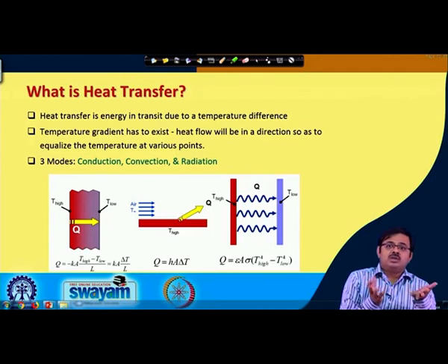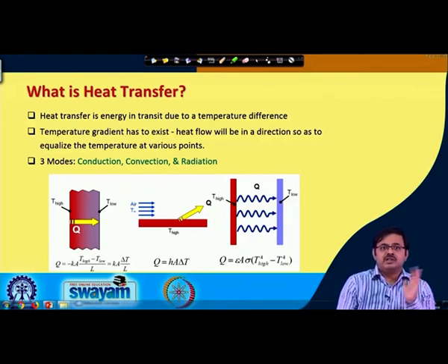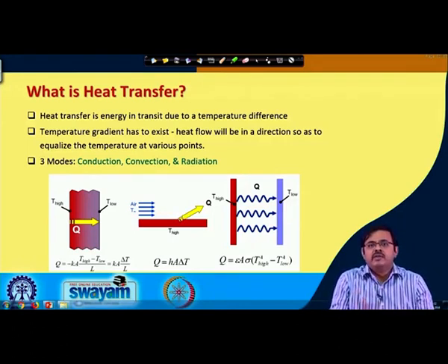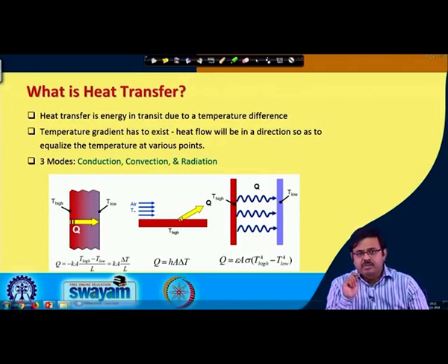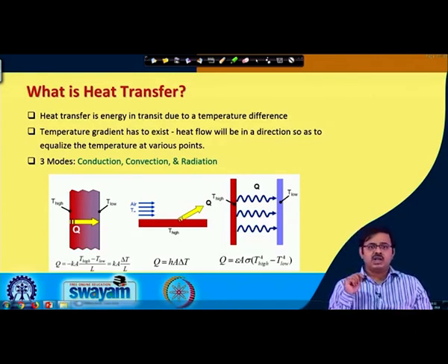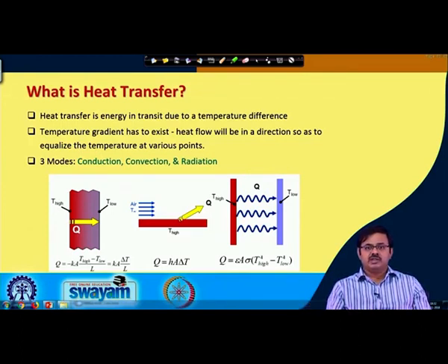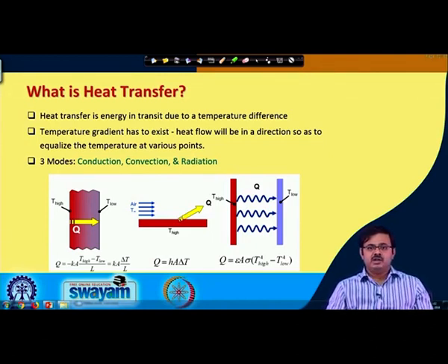And it also depends on boundary conditions in terms of what is the temperature, whether it is uniform temperature or non-uniform temperature, and so on and so forth. We will look at all those later. But what I am trying to say is, unlike a solid like copper, where the thermal conductivity is whatever, 400 watts per meter Kelvin at a certain temperature, for heat transfer coefficient, if you ask me, I am having airflow over a flat plate, what is going to be my heat transfer coefficient?